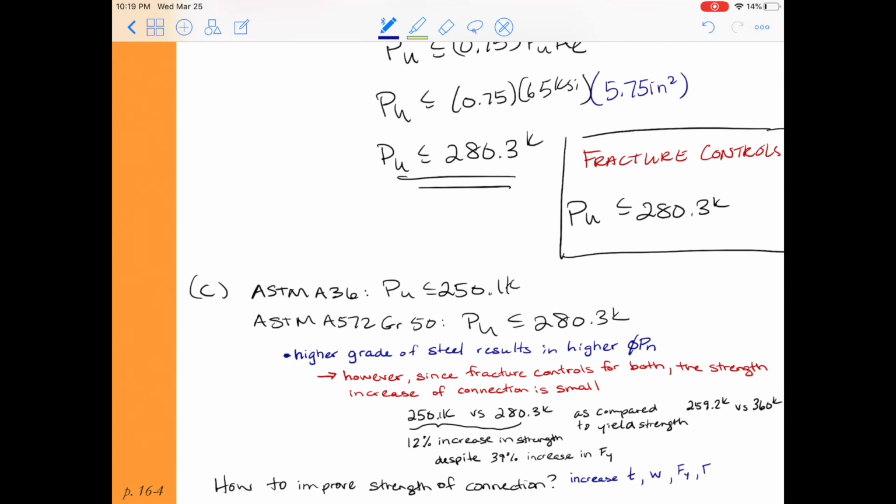And finally, we could look at decreasing perhaps the hole diameters, right? Because in the net section area, we had to lose those hole diameters. Now, again, this is all subject to making sure that a lower size bolt diameter would still work for your strength.